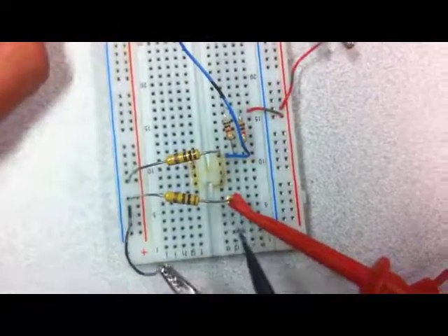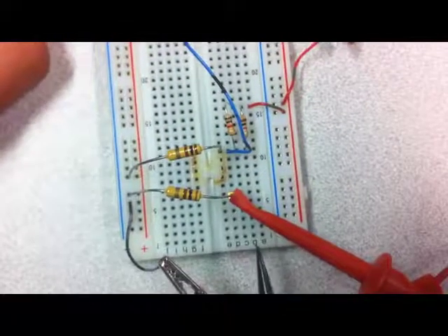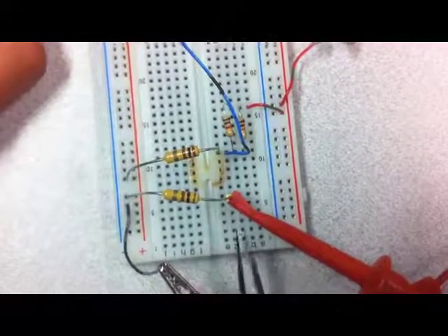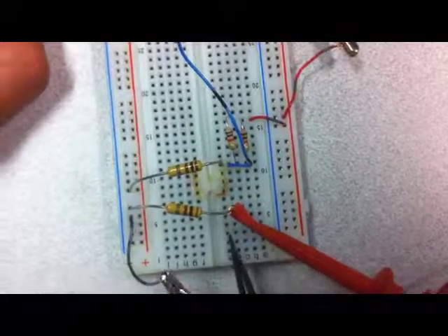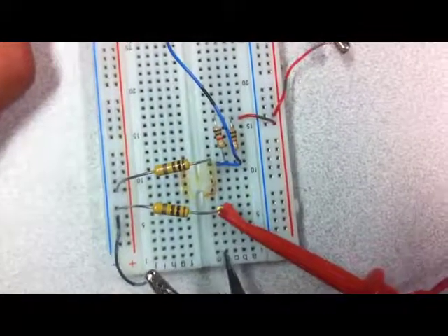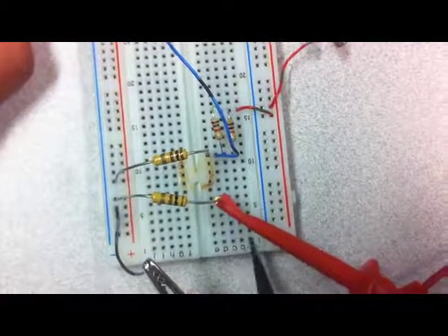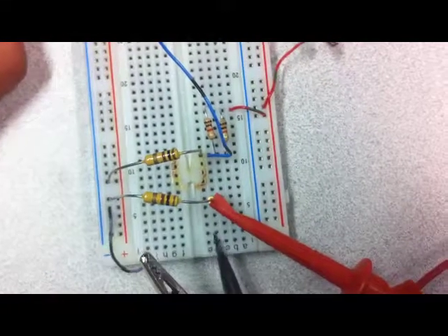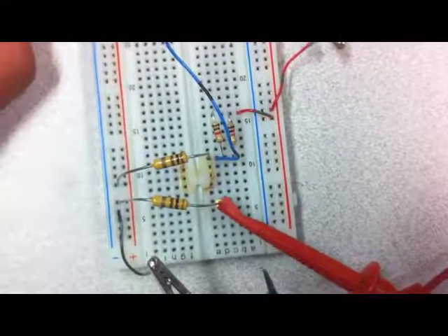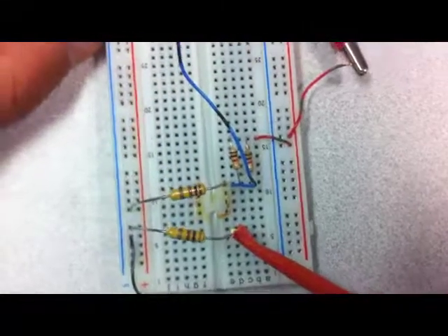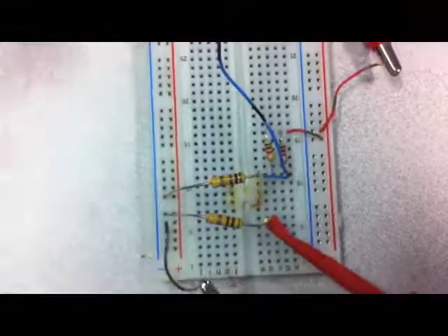Then in the middle of the breadboard, we've got this part, and you can see the letters A, B, C, D, E. This section of the breadboard, all the connections are made horizontally. So all of these pins are connected, and then the next row is connected horizontally, but between rows there's no connection. So this is the circuit that we have set up for our current divider.